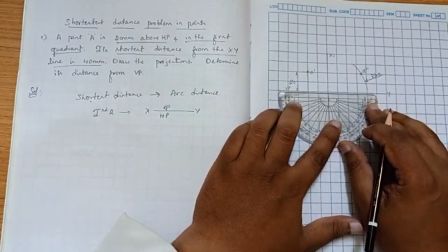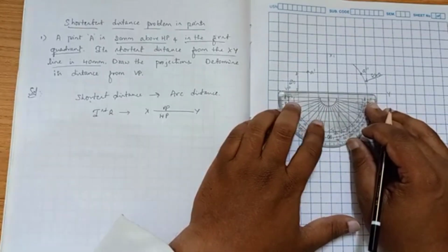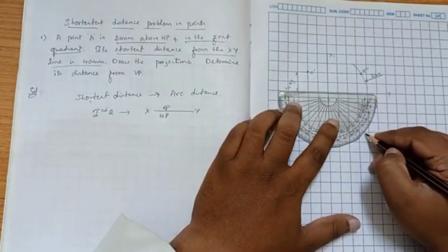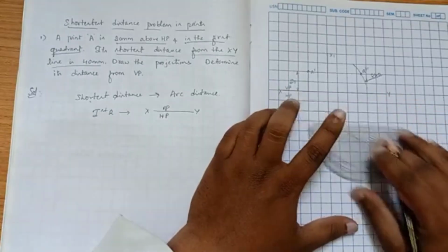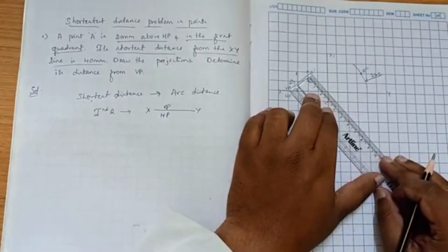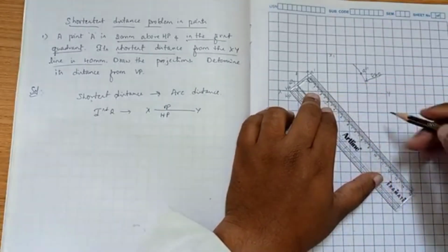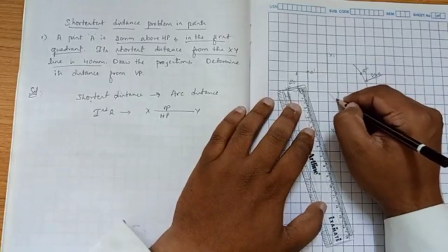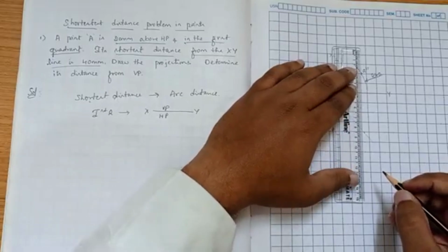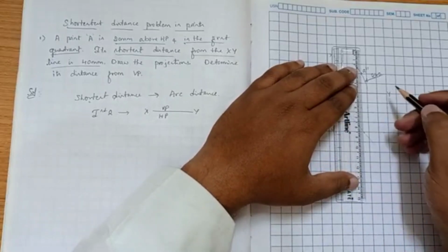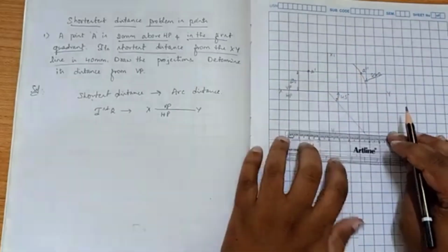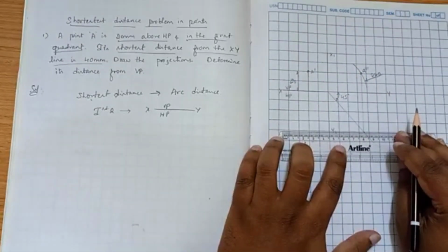All the three views you have to draw, right? So for that we'll be drawing a 45-degree angle line. We can mark a point here, so this is our 45-degree angle line. Now from this side view we draw a vertical line until it touches the 45-degree angle line, and from this point you draw a straight horizontal line.